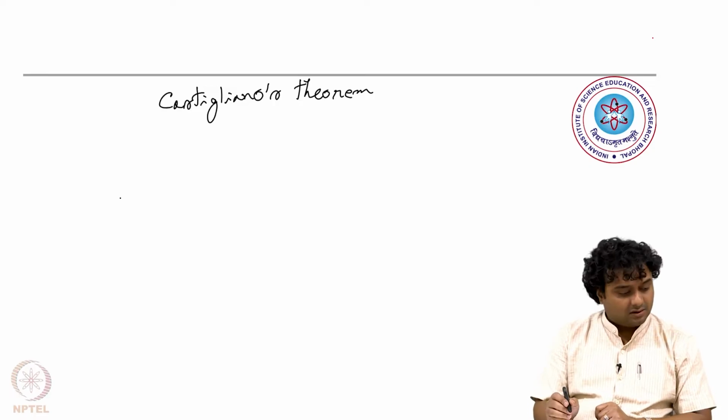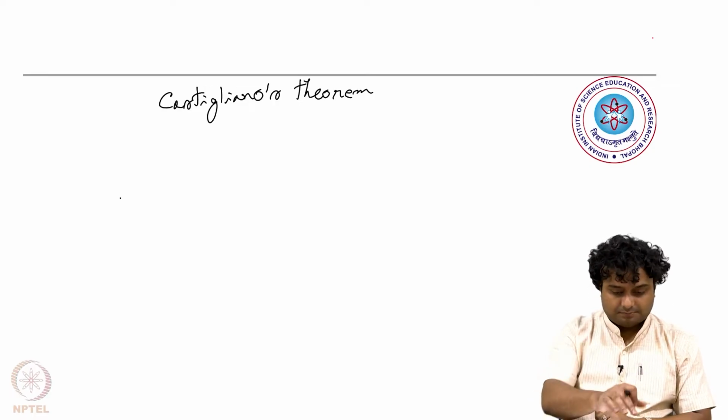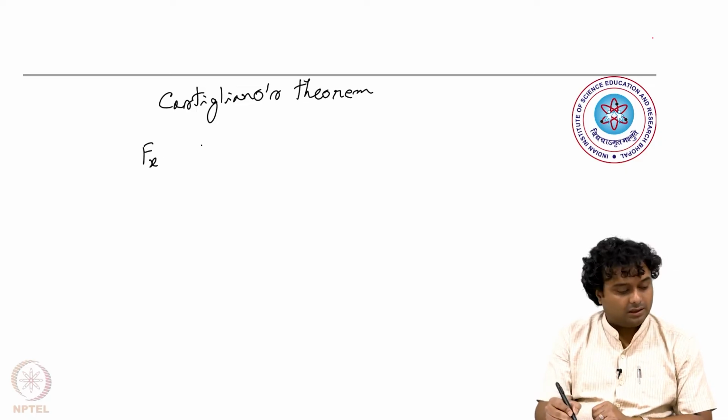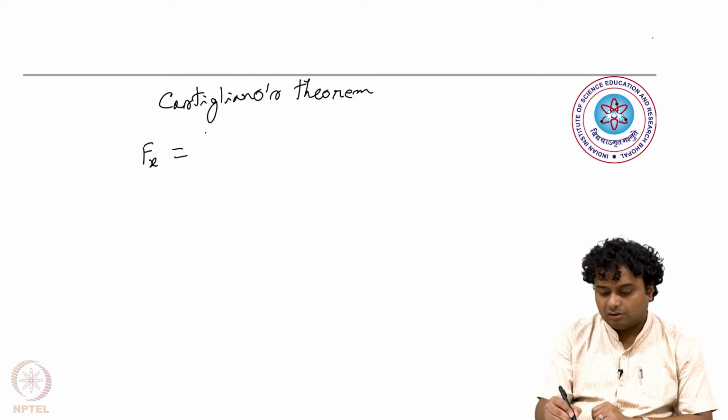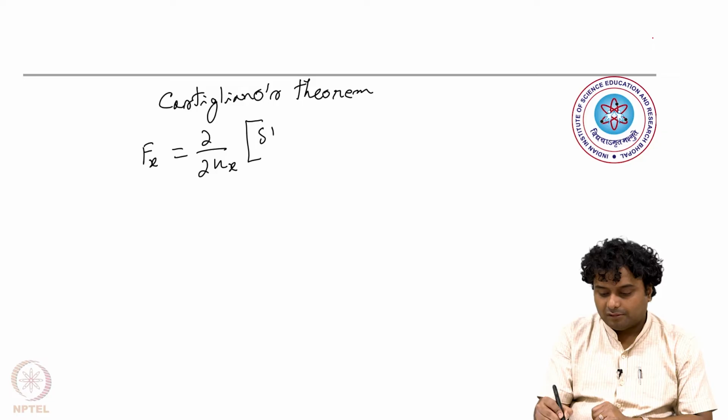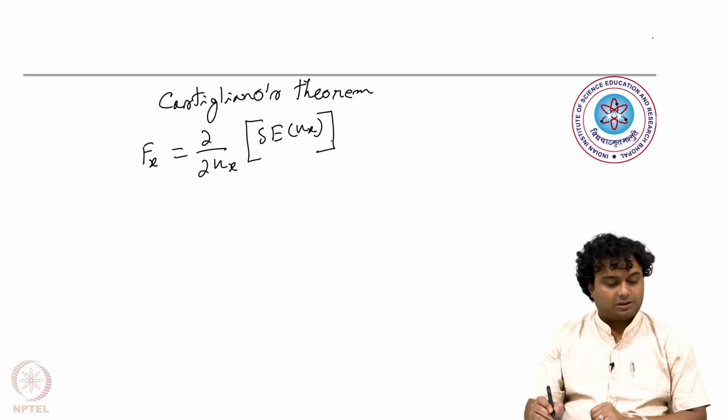So what does this theorem say? The theorem says the force in the x direction, Fx, is equal to the partial derivative with respect to the deflection in that direction of the total strain energy, expressed as a function of deflection.